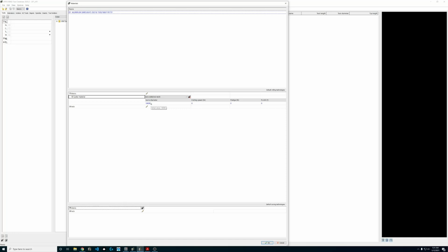So what we're going to do now is take a manufacturer's cutting speed data, relative to the tool diameters that are important to us, and put it in here and actually use this data for mathematical calculations for the tool. This is where hyperMILL gets really strong. We can use basic surface footage and chip load data and actually build out formulas for radial chip thinning or effective diameter of ball end mills, and it gets really, really strong. But it starts with this.